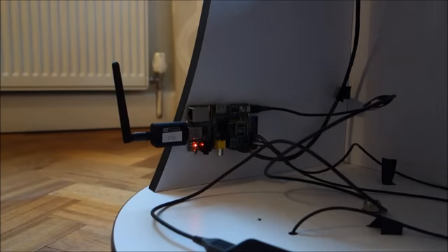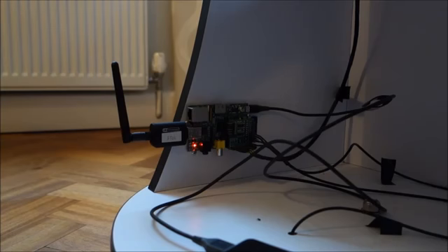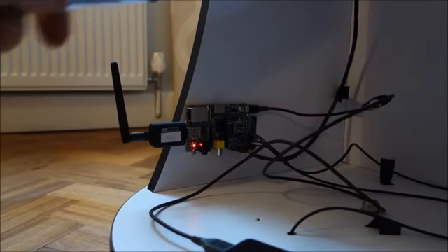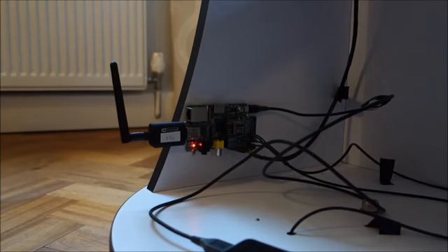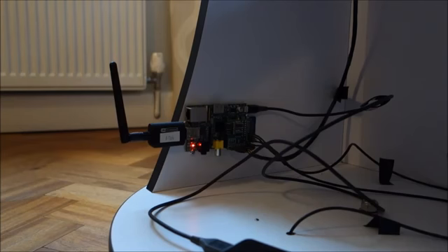And the second reason is that on the Arduino you can only do floating point calculations with decimal precision of about 6 decimal places, which isn't really enough to do the astronomical coordinate conversions on the board itself. You don't actually have to do them on the board. You could do them on the laptop, but I quite like to have the system a standalone system where you don't need the laptop in order to be able to do the coordinate conversions and print them out on the LCD screen.